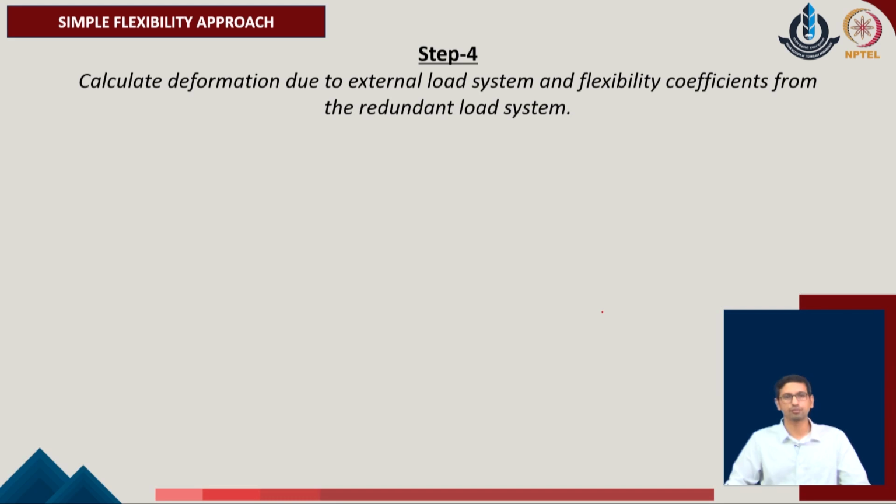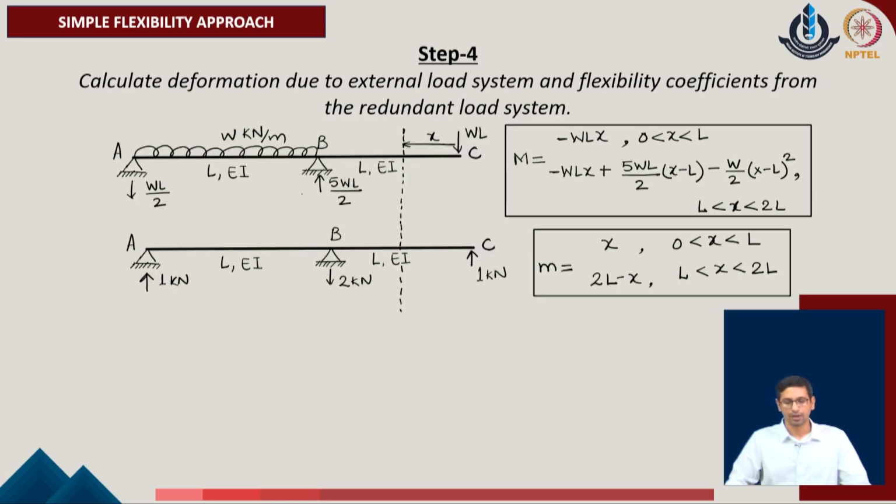As we go ahead with step 4, we calculate the deformation due to the external load system as well as the flexibility coefficients for the redundant system which has been identified. To calculate the deformation due to the external load system, this is the external load system which we have defined. With respect to this system, I want to evaluate the deformation over here, and the deformation will be evaluated in the direction of the redundant of the given problem. That is why we are looking to evaluate the displacement at the given position.